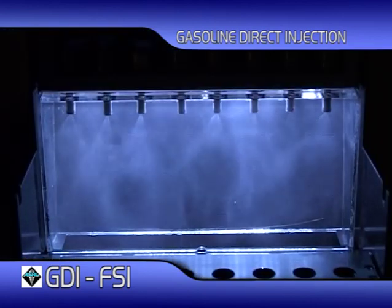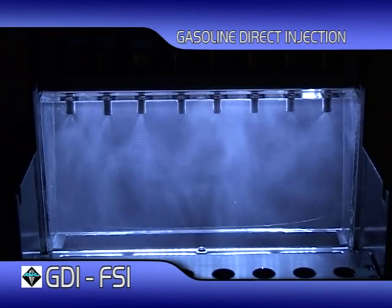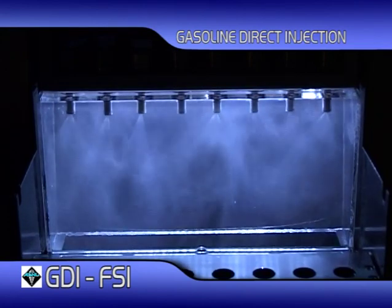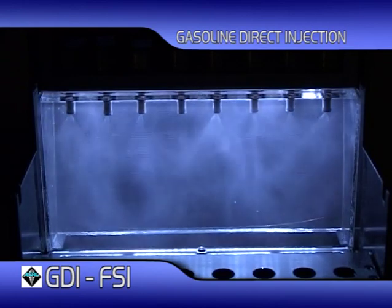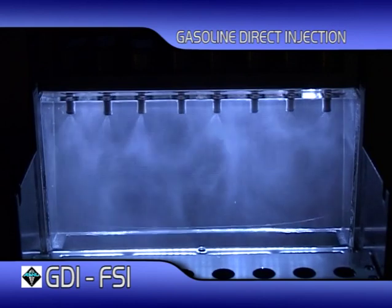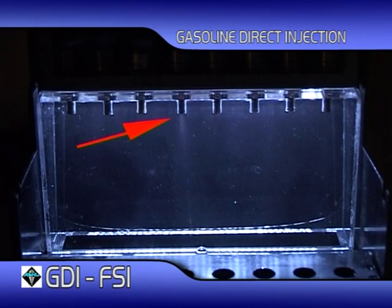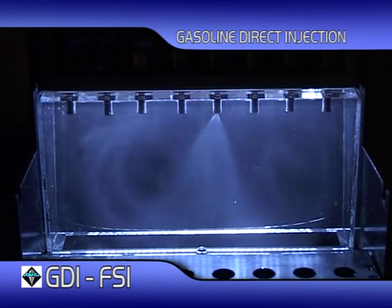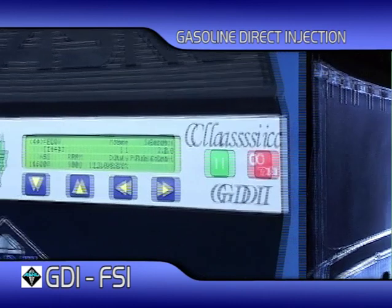In this clip, the RPM has been increased, and although the injectors seem like they are running simultaneously, they are in fact running sequentially. The design of these injectors does mean that they are a lot noisier than a standard injector. When we switch to single injector mode, you can see a further deterioration in injectors number 4 and number 6. This lack of fuel could cause detonation on the piston and cause considerable damage to the engine.